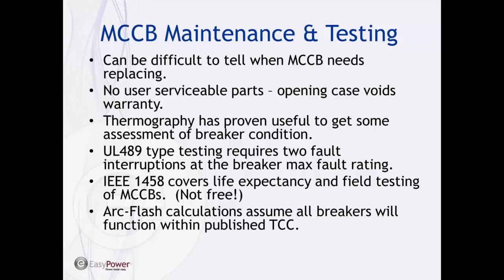The second issue is that per UL and the manufacturers, the molded case circuit breaker really has no user serviceable parts. If you open the case on a molded case breaker, you void the warranty. And so typically if the breaker has an issue, you have to replace it. Obviously you can take them apart, but it's not recommended.